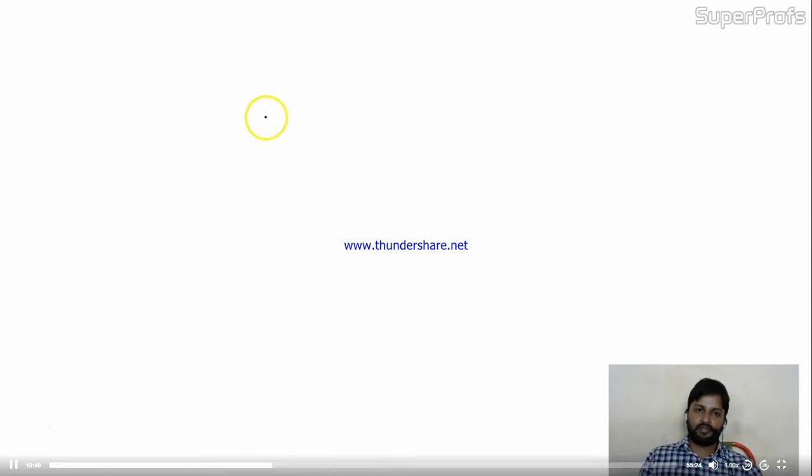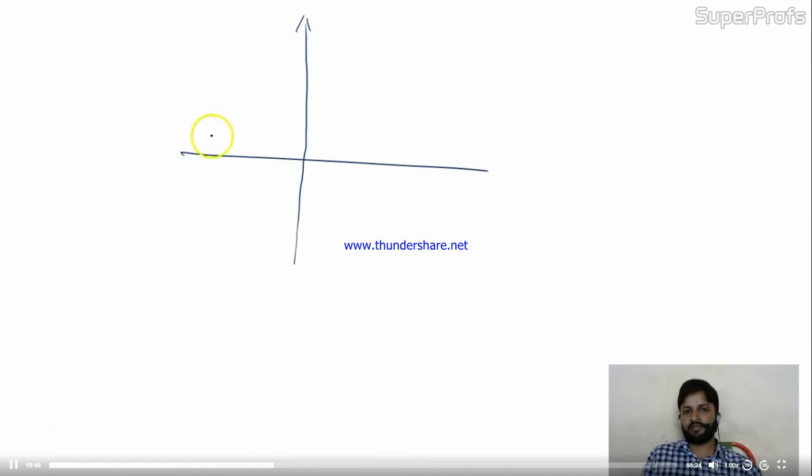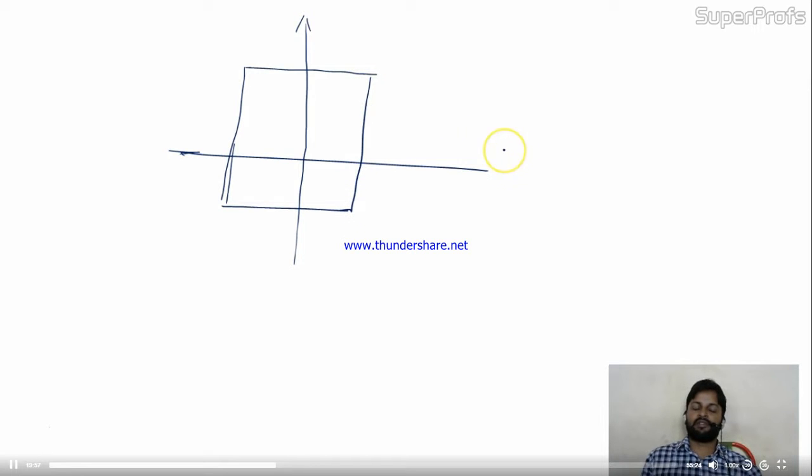So what is the hysteresis width, and what are the lower and upper points over here? Let's see the hysteresis over here. Before that, what is the formula? The formula is minus R2 by R1 of V naught.